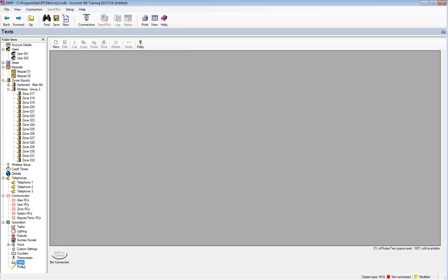And if there's a certain piece of equipment that we don't currently integrate with, you can use the XSP and adjust its baud rate and so forth to match the other equipment, and you can send custom ASCII strings for some limited communication back and forth between the two. Obviously, each command would require its own unique ASCII string, but you can create multiple ASCII strings and text messages within the text window here.